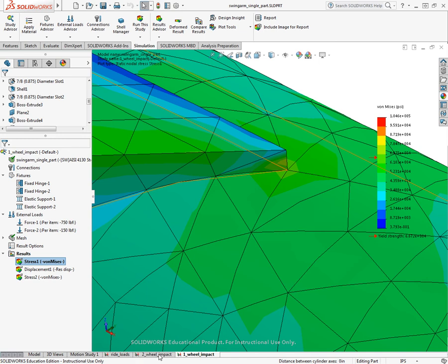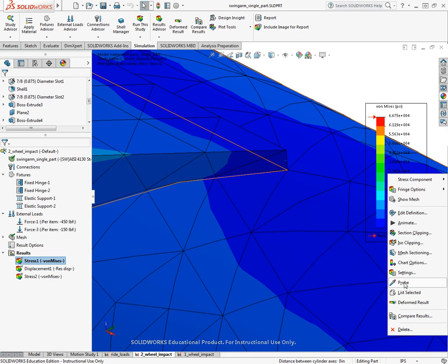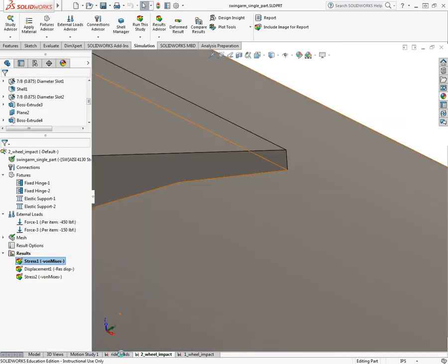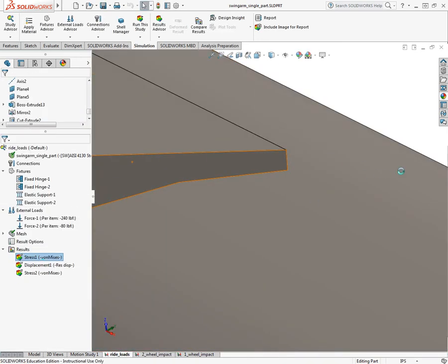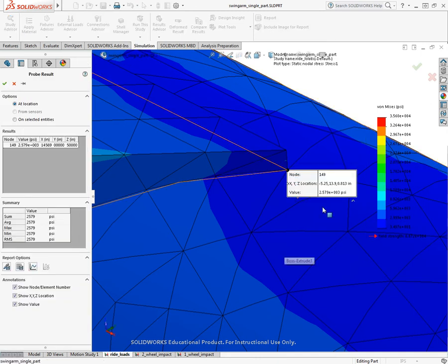And I do it the same way. I take that stress, I go to the next model, grab the stress at the exact same node, 48,360, go to the first load case, do the same thing, 25.79, and with those three stresses I can apply Miner's rule and calculate the total life N1 of the part at that location. Essentially what I'm looking for is the location where the total life N1 is lowest.